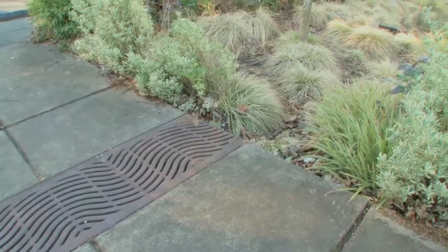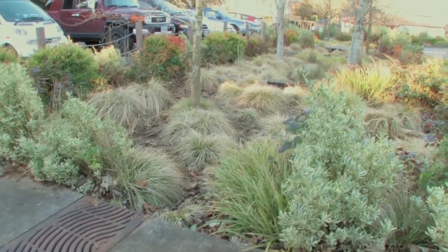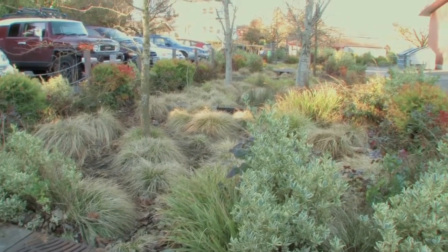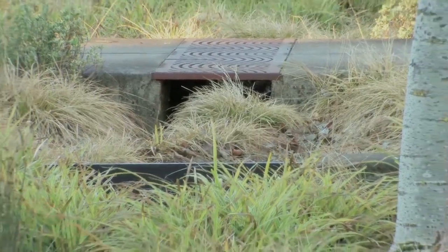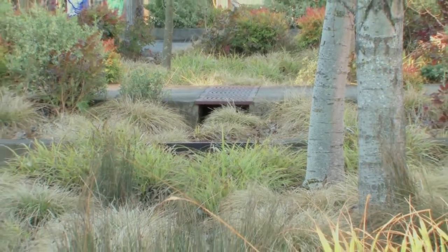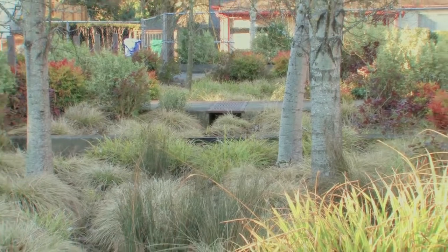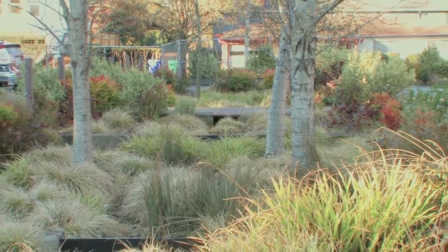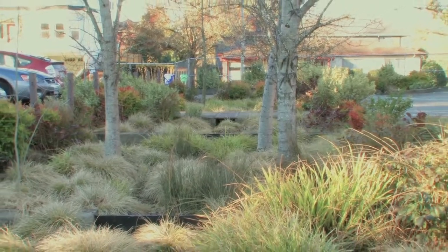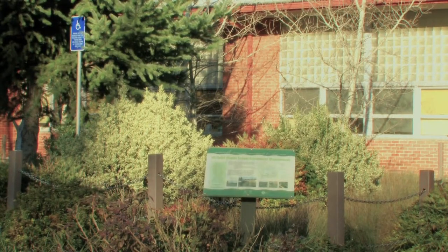The parking lot was retrofitted with a 1,400 square foot swale and a 200 square foot planter. Together, the systems manage runoff from 15,000 square feet of asphalt. The swale has multiple check dams to retain runoff and promote infiltration. Both the swale and planter are designed in a very large storm event to overflow safely toward the entrance of the parking lot, the street, and curb extension. This project is an example of how a retrofit project incorporated improvements that went beyond the immediate goal of rainwater management.